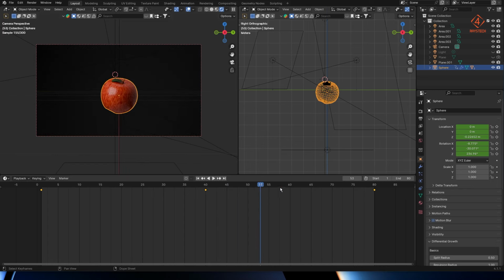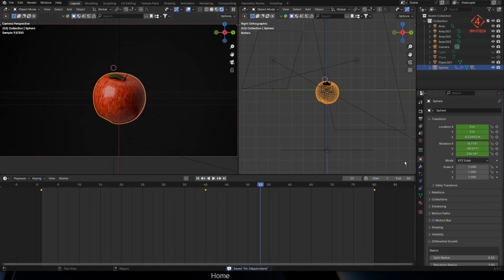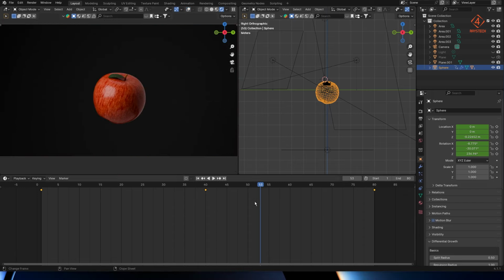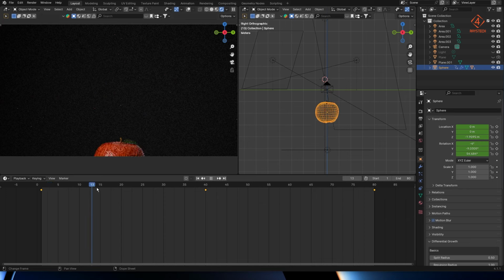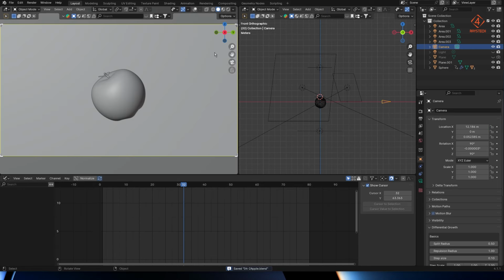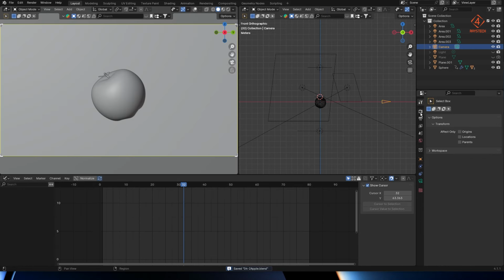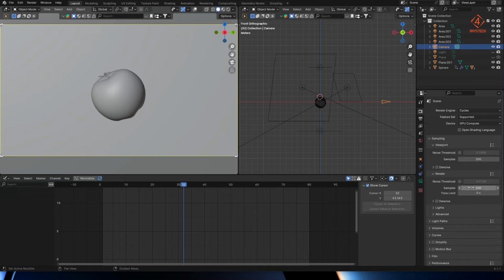You can switch over to render view and you can see that. To switch over to render view, you can always press Z and change from wireframe to texture to render and so on. Turn off the overlay viewers. So now you've got nothing coming up on top, and we've got ourselves a complete animation.